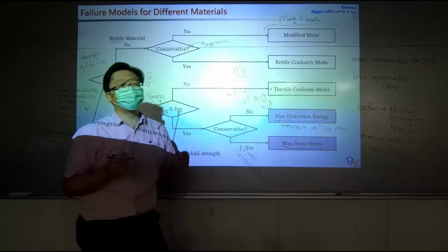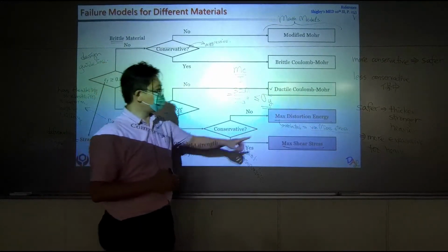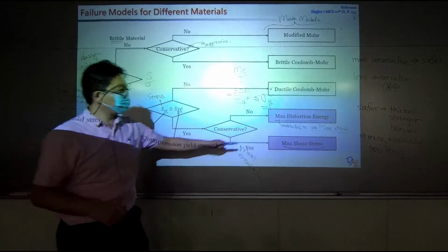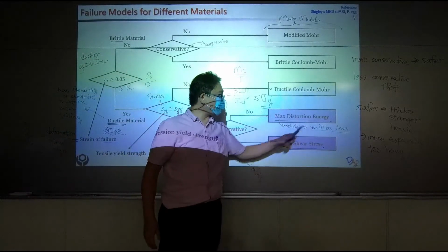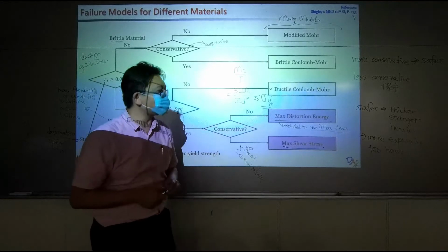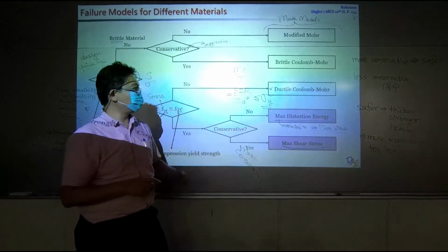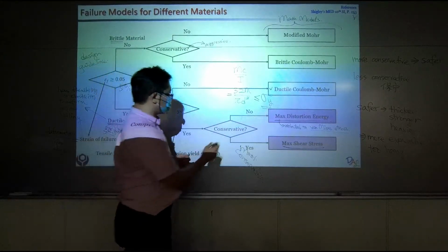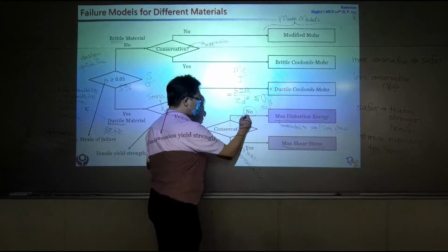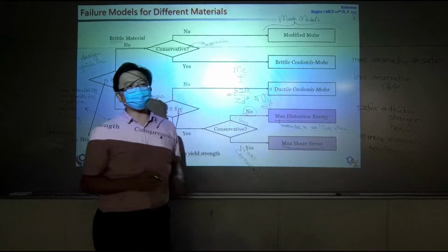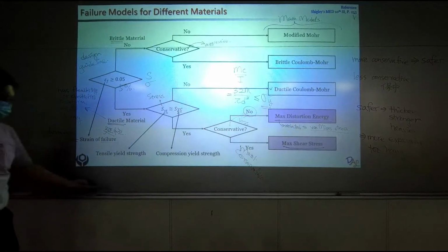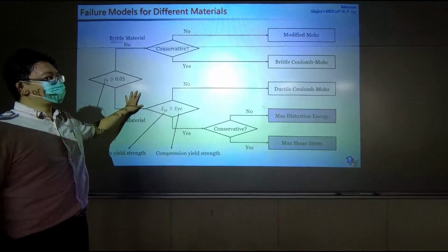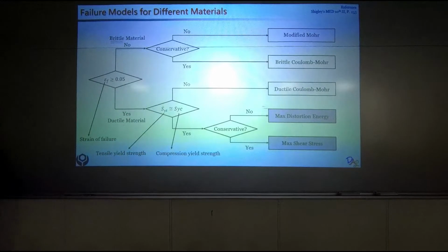Okay? And in many software packages, they use von Mises stress a lot. And you need to know, when you use software and you decide to use von Mises stress, you are actually being less conservative, because you are less conservative if you use the model. Okay? So you need to know that. Like this slide can be done in 10 minutes, but you will miss a lot of key ideas.